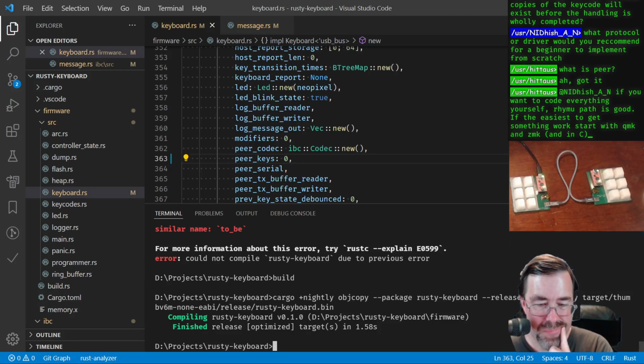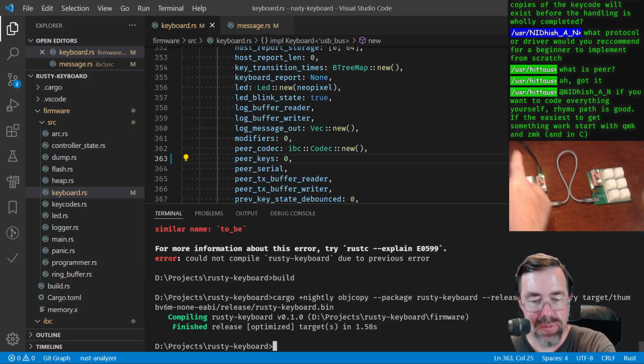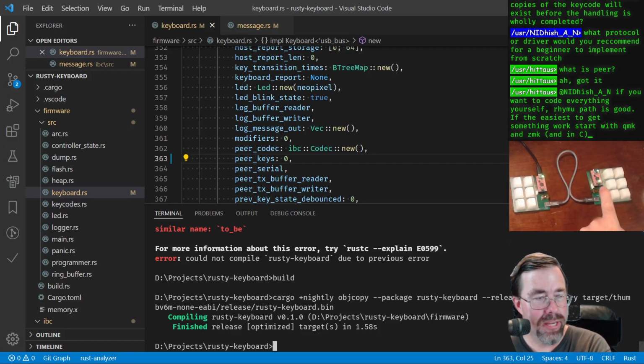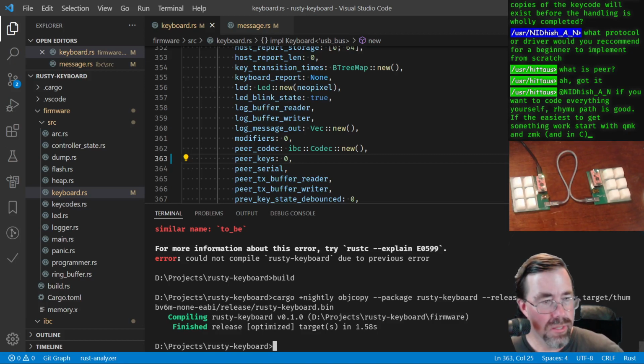And the other function is that when the host sends a new firmware image, the primary's job is to forward it over this cable to the secondary, and then wait until the secondary is done programming the firmware, and then finish programming yourself, and then they both reboot together, which I kind of like how I did that.